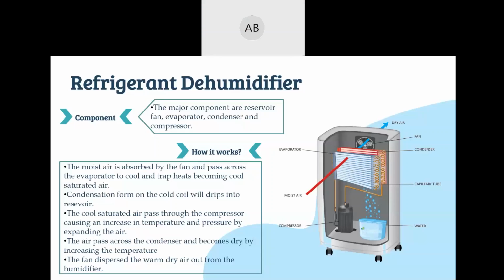I have a question for Listen. What is the purpose of a cooling tower in industry? Okay, Amira, the cooling tower in the industrial sector is used to remove heat and cool down the plant. For example, the heat from the hot water that is produced by the power plant or petroleum refinery plant is absorbed in the cooling tower, and cool water is collected in the basin and is recirculated again in other plants to absorb heat. Okay, this is my answer.